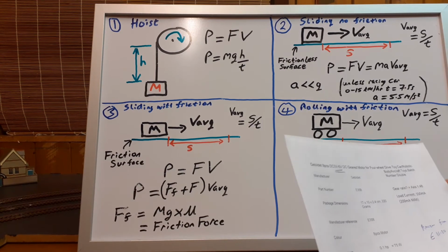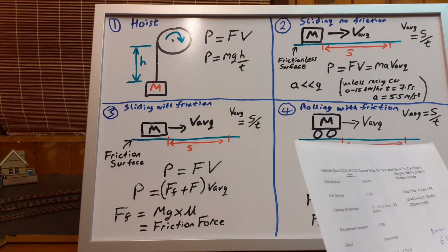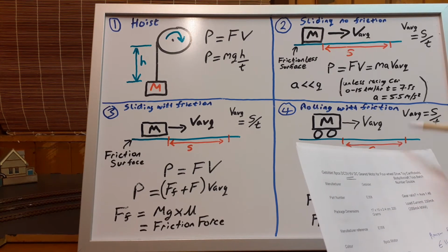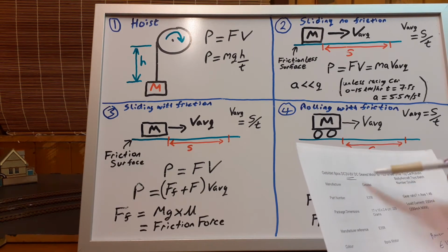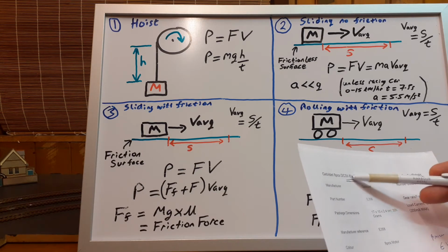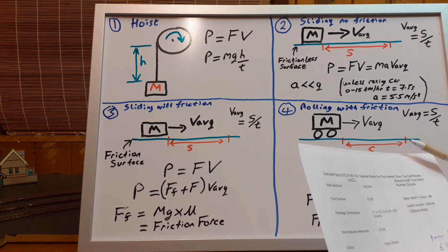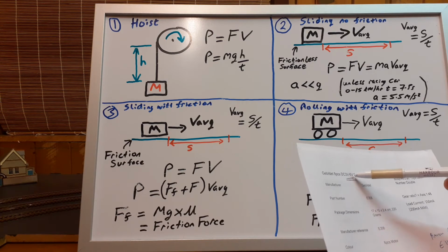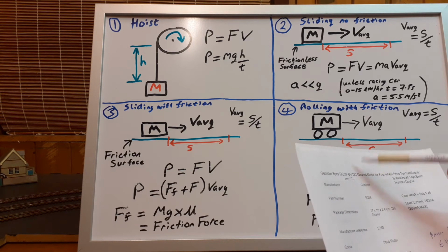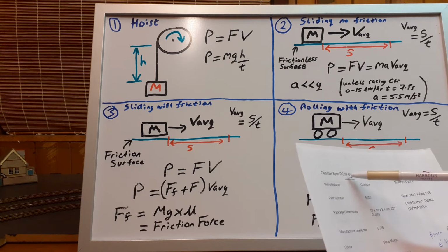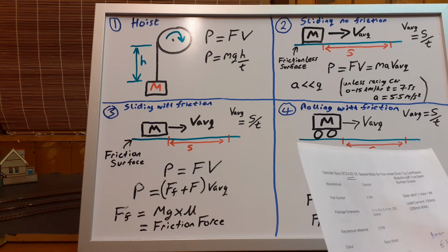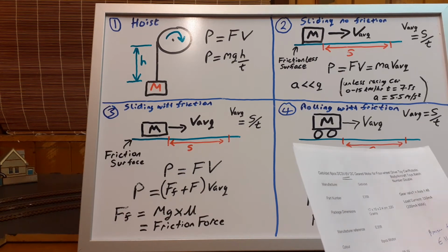Now, sometimes on motor spec sheets, they're giving you the power input, which is the volts by current. And if you go that way with this, it runs at between 3 and 6 volts. In fact, it doesn't. For me, it only runs at 5 volts, and the max I went up to was 6 volts. I didn't want to exceed the 6 volts in case it did damage, but it certainly didn't run at 3 volts, and I needed to go up to 5 volts to run it. Again, be wary of what they say on these sheets.